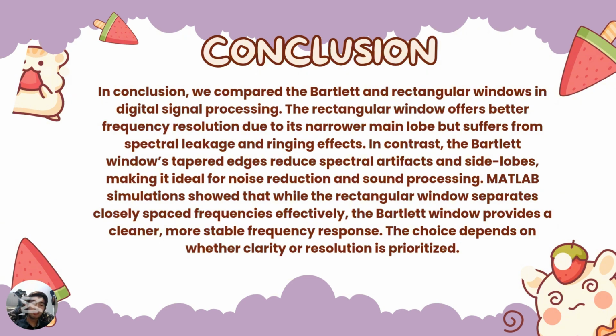The MATLAB simulation also demonstrates the practical implication of these windows in a real-life scenario, such as filtering a noisy signal. While the rectangular window allows for better separation of closely spaced frequencies, the Bartlett window provides a cleaner spectral representation by minimizing high-frequency interference.